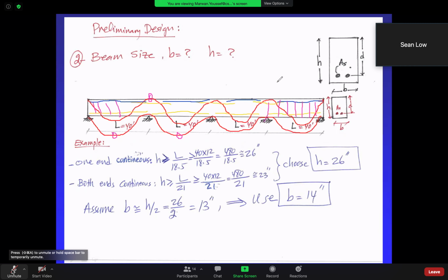Just to confirm, the shear supports are the stirrups, right? Yes. Thank you. Yes, the stirrups is what is going to resist the shearing force that is going to try to break the beam in this action. Like, look at my hands. That's the shear. So the stirrup's going to do that. The longitudinal bar is going to resist the bending of the beam. Okay, that's what it is. Any other questions?